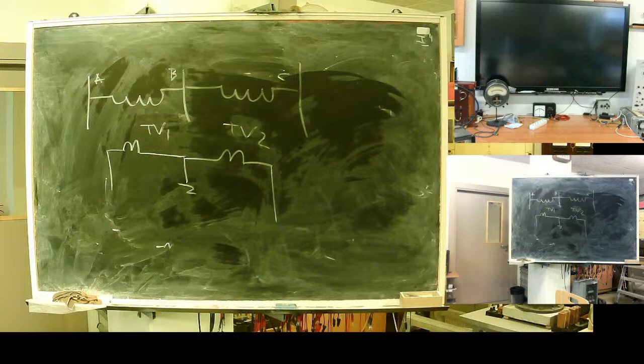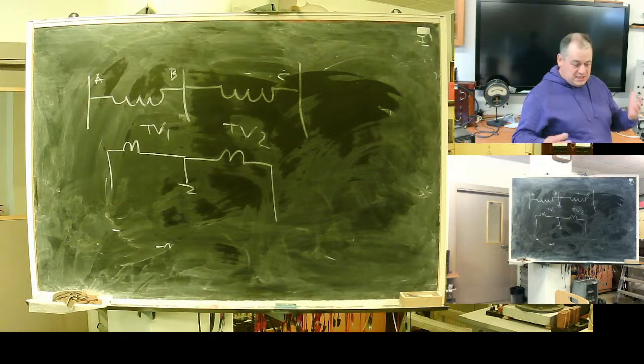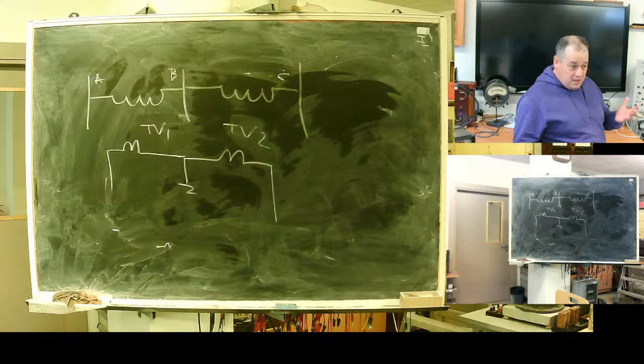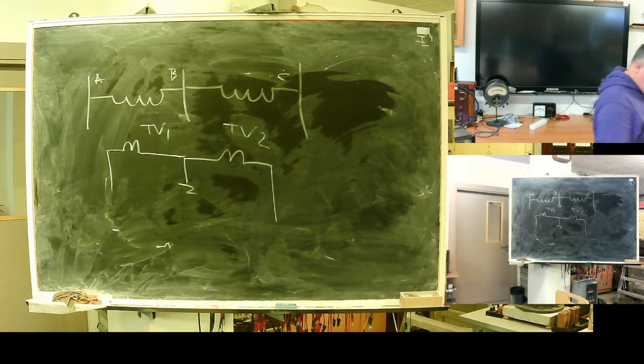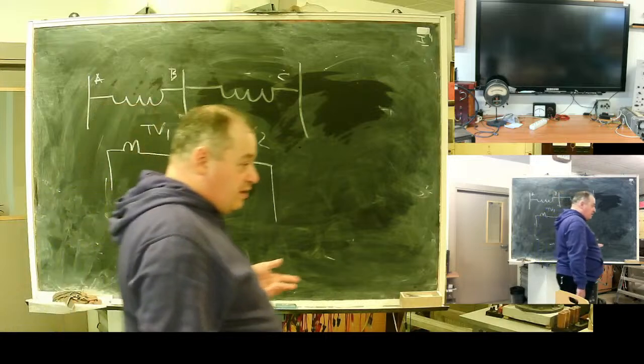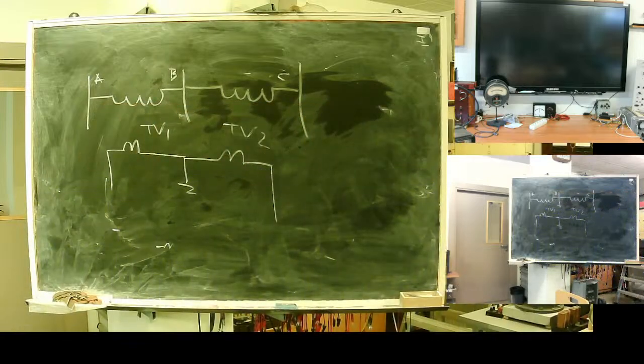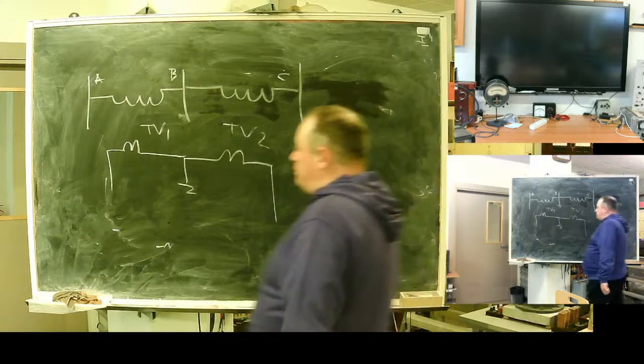So healthy phase voltage makes all this design more reliable. If I use an unhealthy phase, it's less reliable. Because, for example, I have an A phase relay, fault AB, voltage goes to 0, I have a problem to operate.